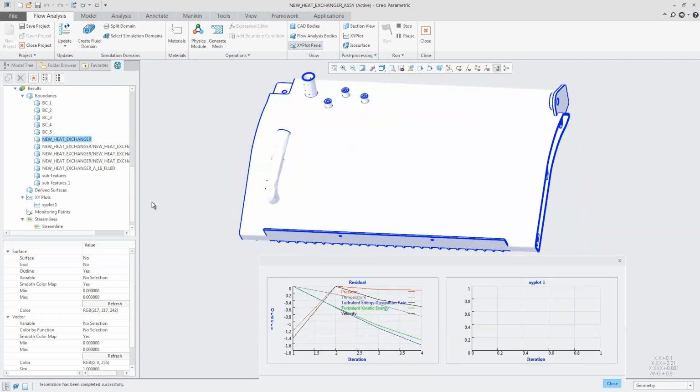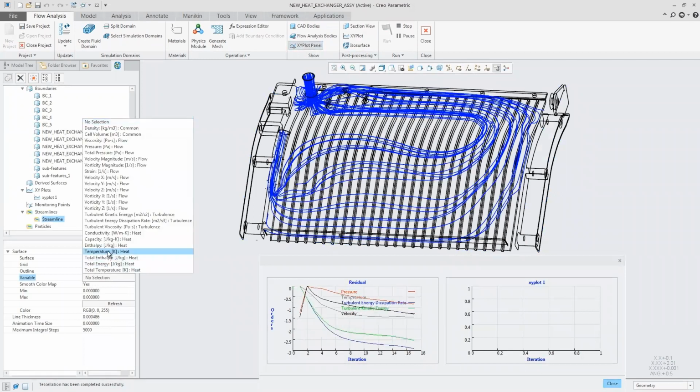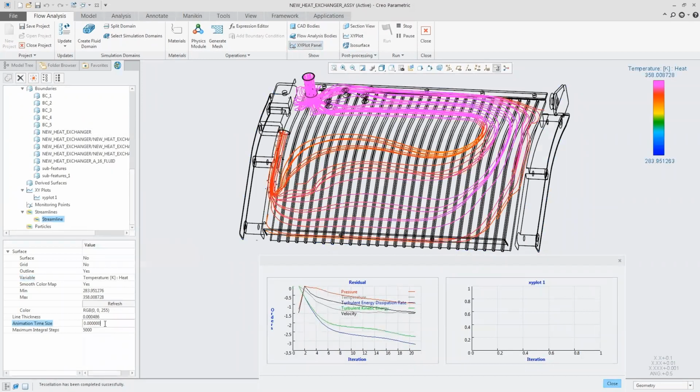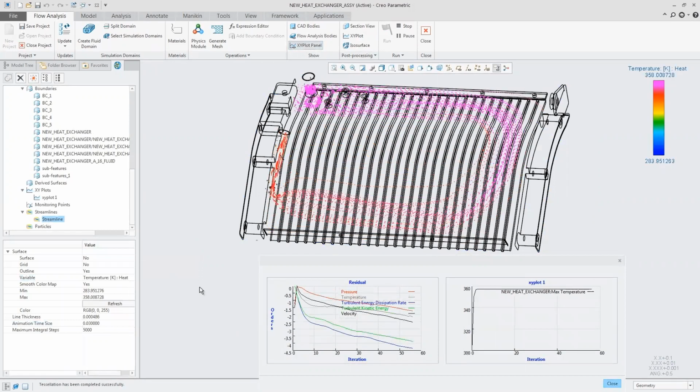And once we have that all laid out, we'll just say what we want to show and go ahead and run the study. And you can see essentially, as soon as I click the button to run the simulation, we're getting data back from the study. I'm able to make changes to the animation style, put it into a form that best displays the information that I want to see. And looking at the plots at the bottom, we can see that our max temperature value has settled out just around 360 degrees Kelvin.